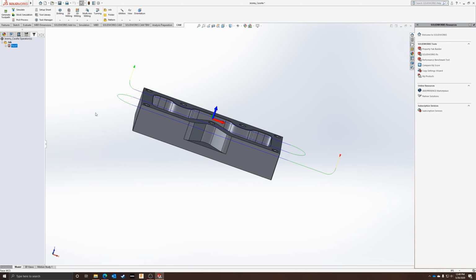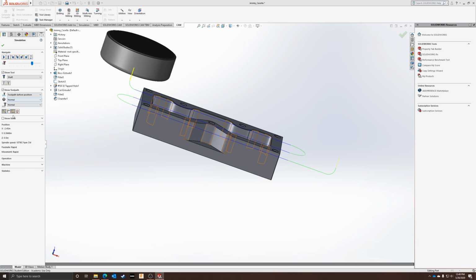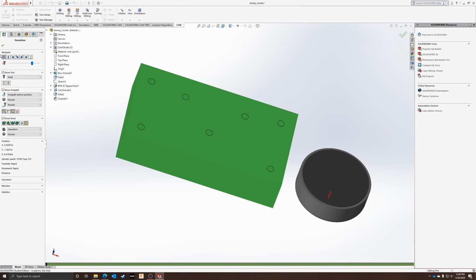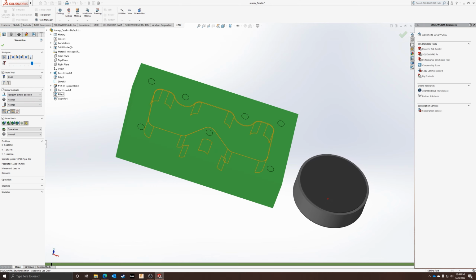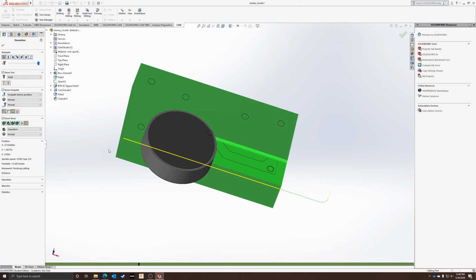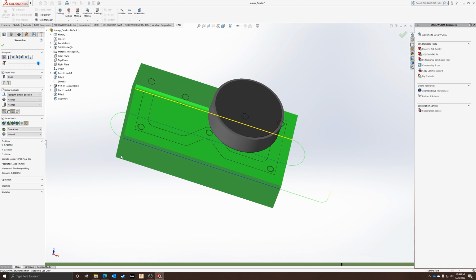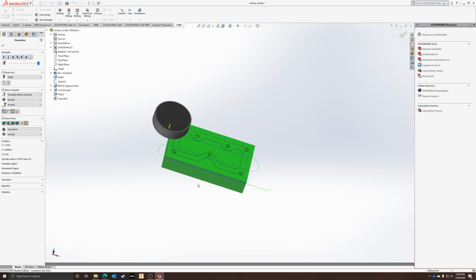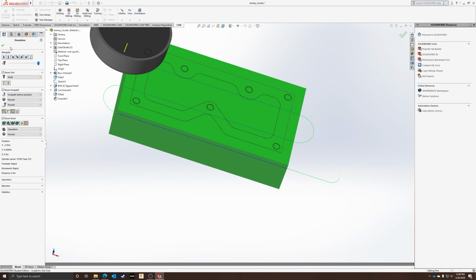So now that we have a facing operation, we will have a theoretically smooth surface. So I can select my job and simulate the whole thing. And when I do and enable stock, you'll see that it's going to come in. It's going to take 60% of the tool, and it's going to cut back and forth. There we are. It's just super slow. It's going to go back and forth facing down the part. Perfect. And now you can see these lines showing that we are indeed at the surface of the part.